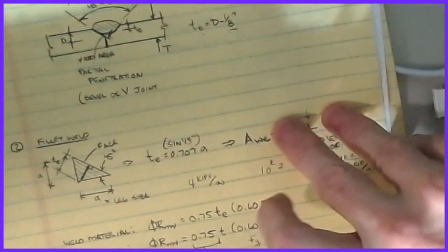All right, with that, I think we will go ahead and stop with our basic welding primer for now. In the video that comes immediately after this one, we'll have a couple of example problems. I'll walk you through how we can decide some things, but hopefully this gives you an understanding of a lot of the different factors and terms associated with welding. Again, remember that there's a minimum size of weld and a maximum size of weld that has to be obeyed, and the weld that you actually choose has to be between those two numbers. If that's not possible, then you have a real issue on your hands, so you've got to be careful to work that out.